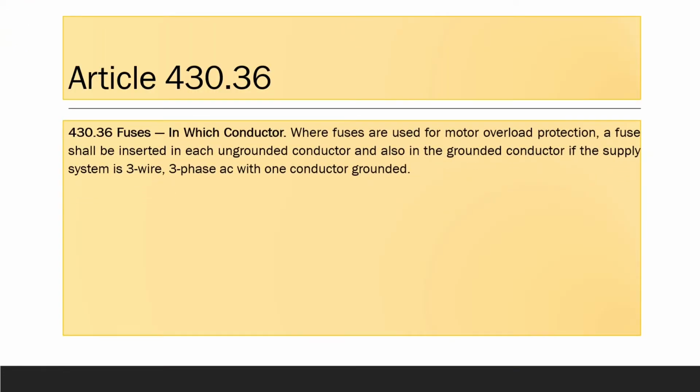Where fuses are used for motor overload protection, a fuse shall be inserted in each ungrounded conductor and also in the grounded conductor if the supply system is 3-wire, 3-phase AC with one conductor grounded.